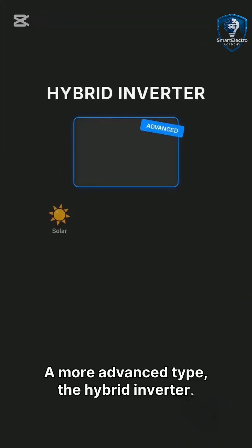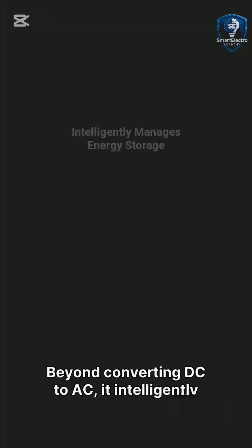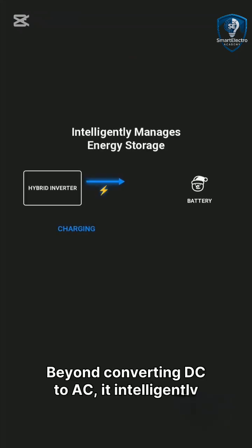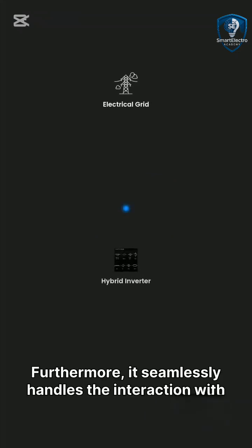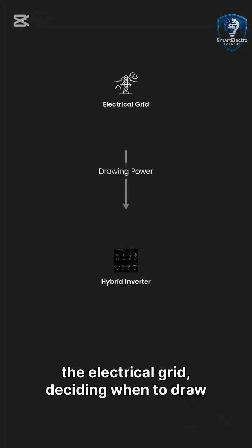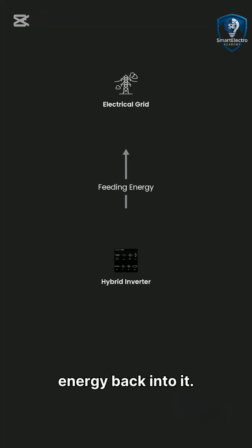A more advanced type, the hybrid inverter, offers even greater versatility in managing your solar energy. Beyond converting DC to AC, it intelligently manages the charging and discharging of energy storage batteries. Furthermore, it seamlessly handles the interaction with the electrical grid, deciding when to draw power from it or feed excess solar energy back into it.